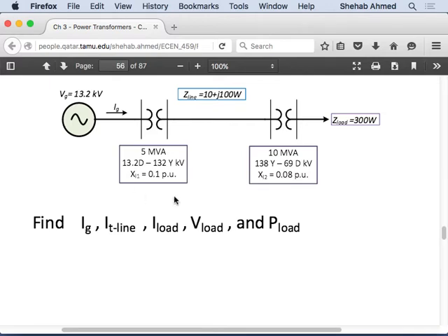And then you write the name and the rated values of the equipment. If you're given those values in the text, write them down, and then chop up the circuit into zones. One zone to the left of this transformer, one zone in this area, one zone to the right of this transformer. So I have three zones. The voltage ratings and power ratings of the transformers are different, so you will have to choose voltage bases properly so that you can eliminate these transformers.